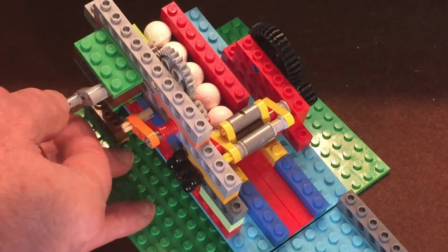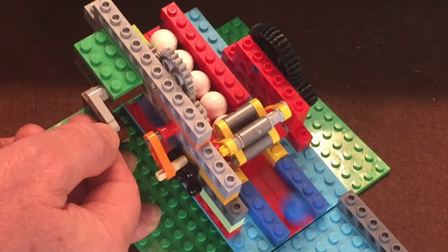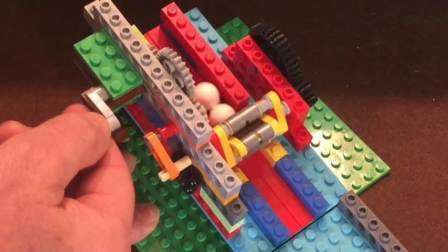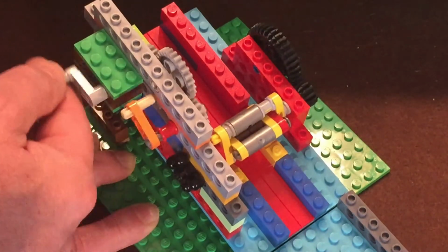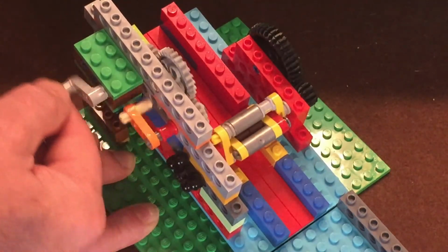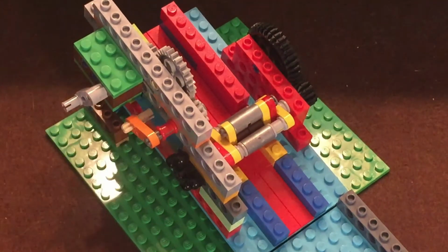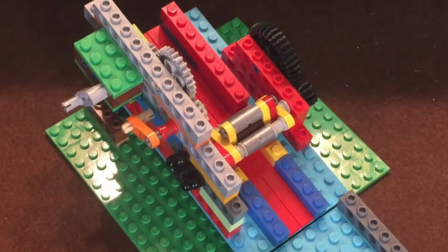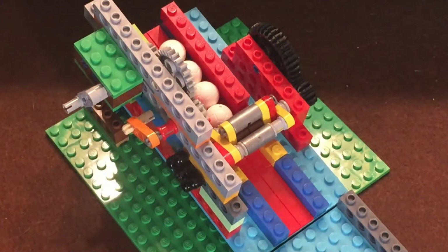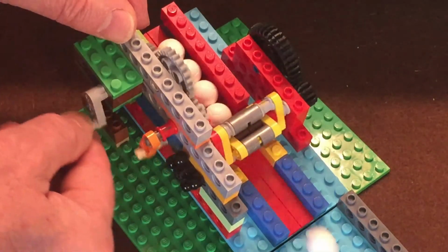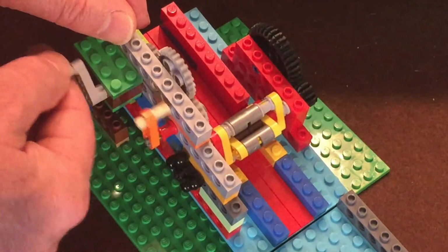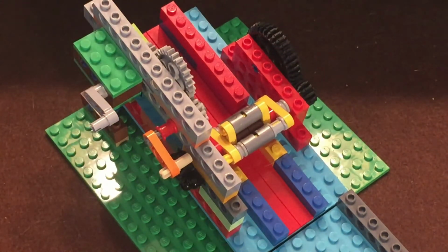Here's another design that I tried. This one will also pass four balls per revolution, but it solves that by using a knob wheel and rotating arm with a pin attached. Every rotation of the arm causes the pin to hit one of the knobs, advancing that wheel by exactly a quarter turn. This allows one ball to pass through at a time. Push is not an issue with this design, but random arrival definitely is. This design is extremely prone to jamming, and the height between the rotating bars and track has to be exact, or it can end up letting more than one ball through at a time.